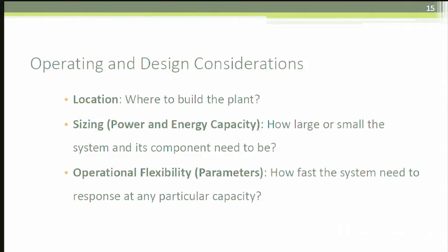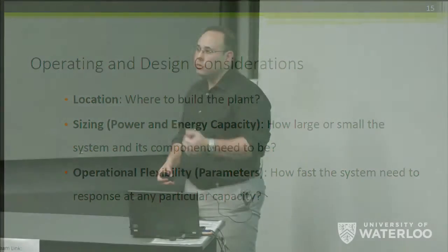Sizing. That means if the kind of regulation service or ancillary service that you need is, say, 50 megawatt in power, you do not need 250 megawatt. So you might actually make more money by having a smaller system. And the same thing goes with the cavern and compression and everything. So you build to the size required for a system. That is part of any study going for CAES. That should be included.